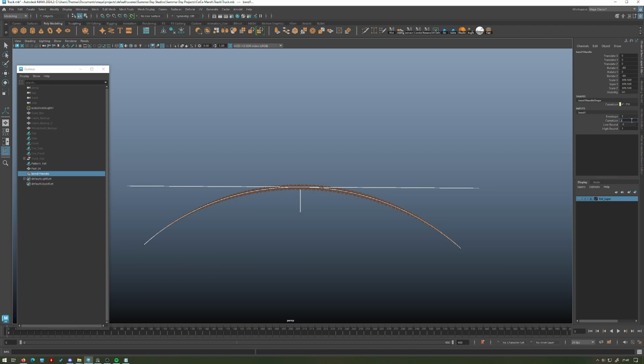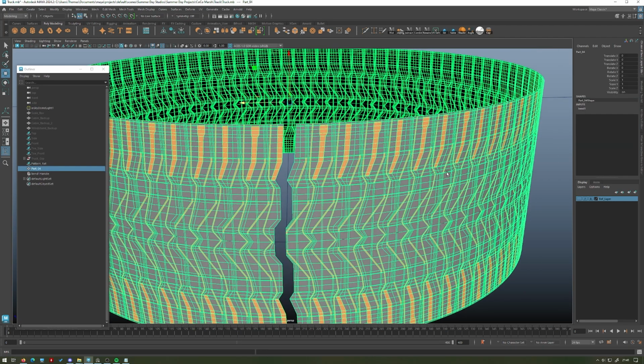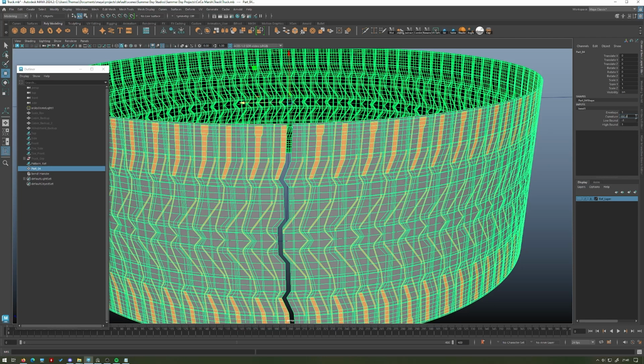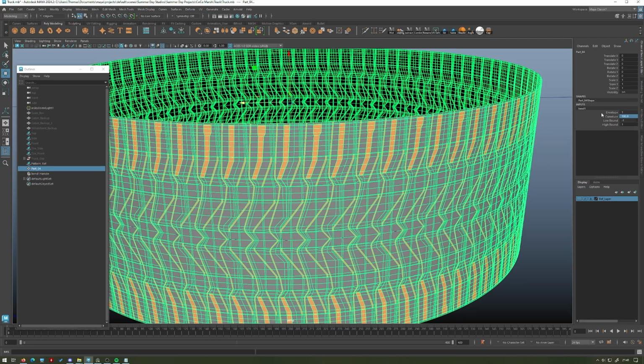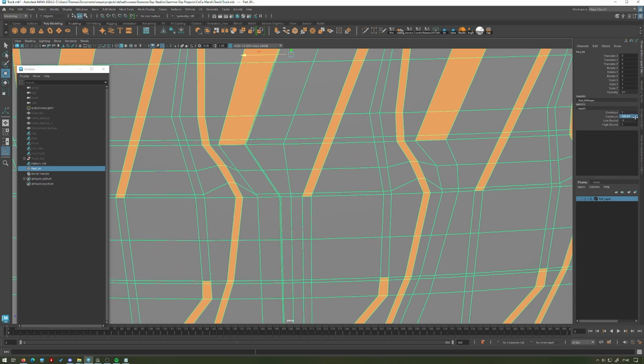So obviously we need this to rotate. Just 90 would only be that way, but we want this to be 180 to come all the way around and connect up. And unfortunately, it doesn't seem to have gone all the way for some reason. It's probably a quirk of the bend handle. So we'll just have to do some little micro adjustments of this. So maybe 180.5, 0.8, that's getting close, 0.9, very, very close, maybe 0.92, 0.93, no, that's slightly too much, 0.925. So this will probably vary for yours, but it's going to be around 180, and then you'll just have to tweak it after the fact.